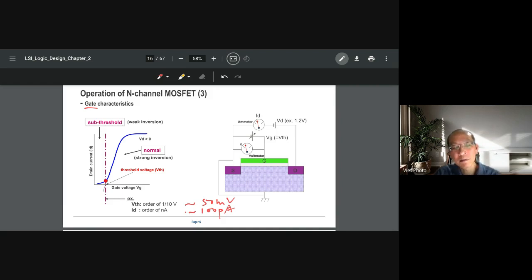Again, one more thing. To have a higher speed, you need higher current, and the current is proportional to the VDD, right? It's common sense: you put a higher voltage, you get a higher current. Put it simply, if you call this one R, the resistance, the current is voltage divided by resistance, right? So the higher the voltage, the higher the current, the higher the speed. But now the voltage is scaling down, because the voltage is limited by this metal oxide.